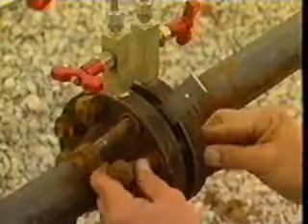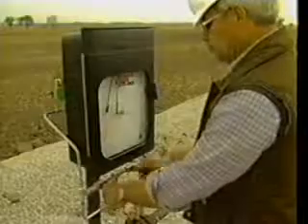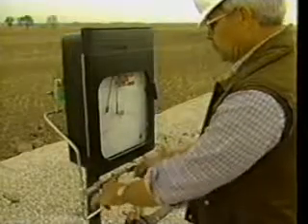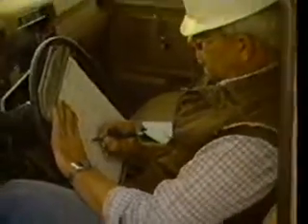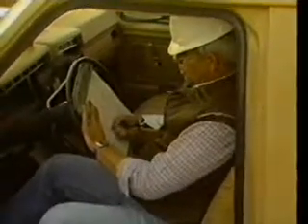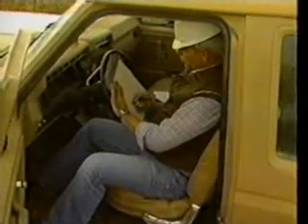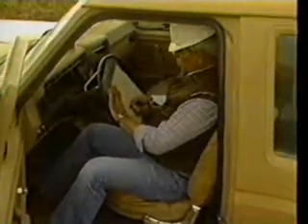After replacing the orifice plate, put the meter station back in service. Check for leaks and note the flow rate and recorder operation. Finally, complete the paperwork for all service performed. Remember, witness all activities and document all findings. Then sign the report. Never sign a blank form for tests not witnessed.